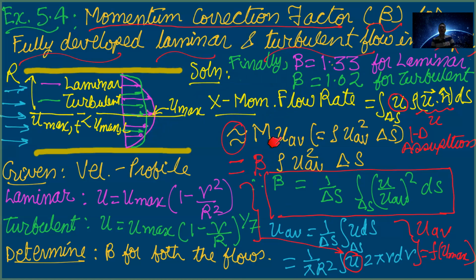So if you are given a laminar flow, even in a nozzle, you need to take this into account for a more accurate calculation. However, for most of the problems given, you can ignore it. But in certain problems, if you are already given a beta, then you need to consider it.